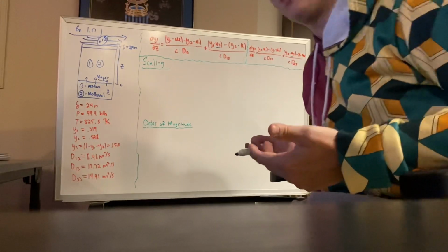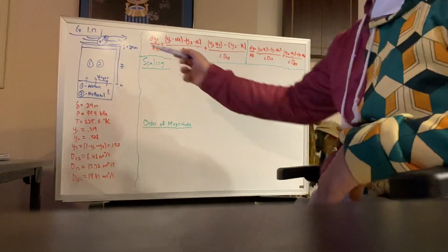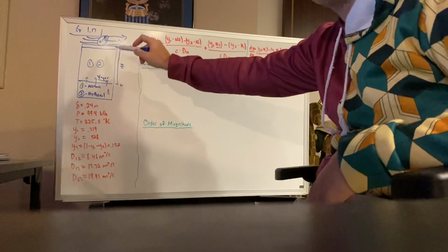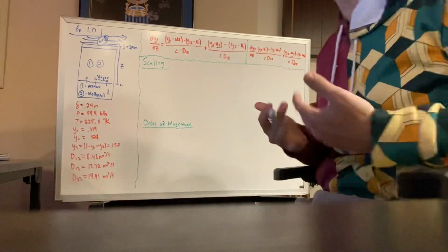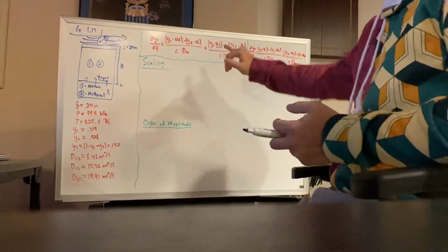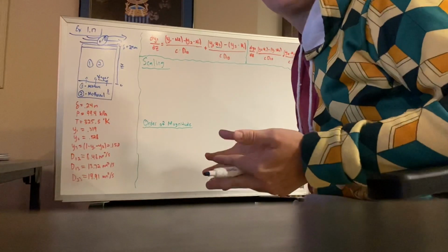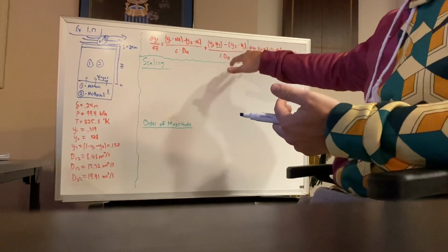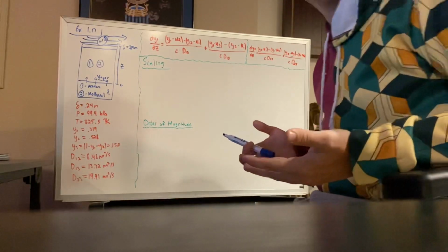And really, when we're looking at it, we see that we have specific variables, N3, which would be the molar flux of air throughout the system. Because air is being blown over at a high rate, it's not diffusing down. So there's no air diffusing down into the system here. We can really take this out of the system and make it 0 because there's no movement of air down into the tube. And so these N3s will be equal to 0. And by multiplying these together, it takes away the entire term, because multiplying by 0 gives you 0. Then you're going to be giving a negative on the right side of that coefficient, but that'll be coming down to another time.